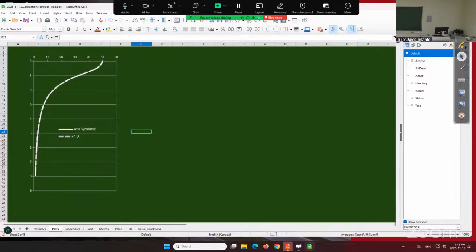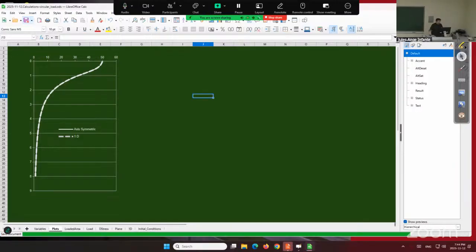At a position of 0, we get exactly the same curve as by using the formula for 1D. So we have higher confidence in our stress distribution, because we get the same value under the center of the foundation.